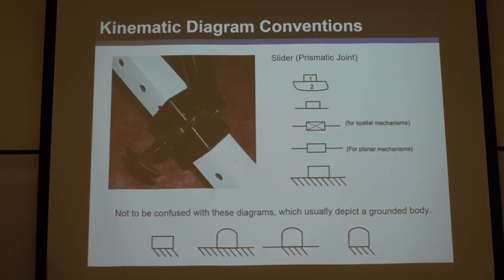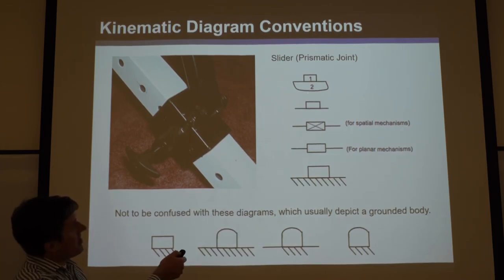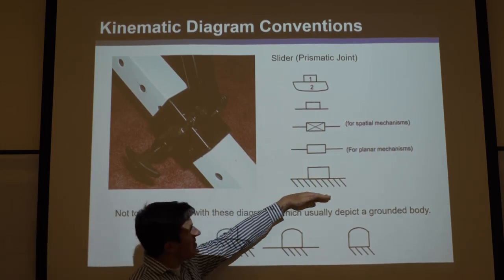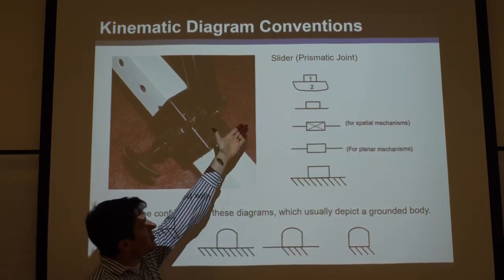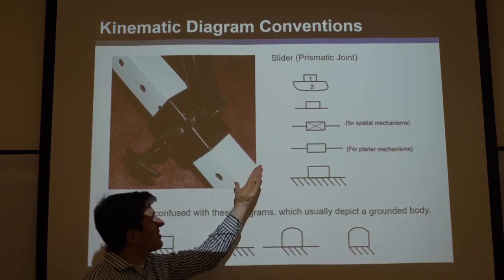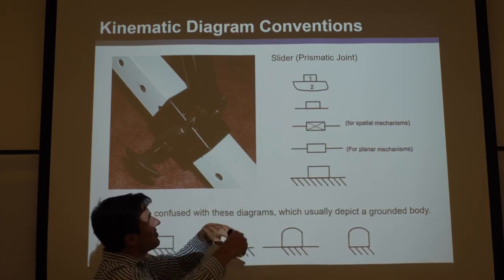Okay, so slider joints are actually really confusing, especially when you think about how you show prism joints or slider joints, right? When you compare it with how things are drawn in skeleton diagrams for fixed or grounded bodies. Okay, so I'll show you all these examples. Everything above here is a slider prism joint where you could draw it in a skeleton diagram. At the top, they actually took the time to draw the 2 different links and label them, so that one's actually clear. That means they slide transverse with each other.